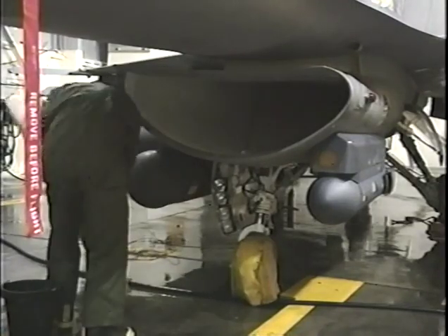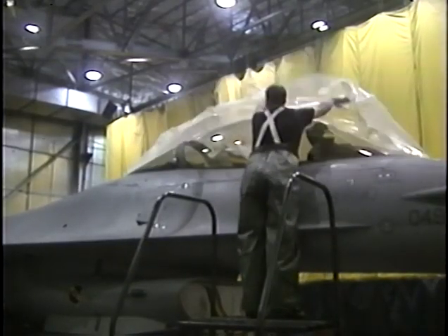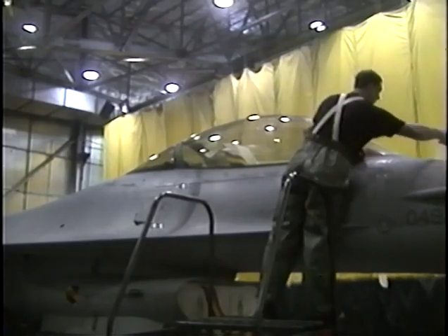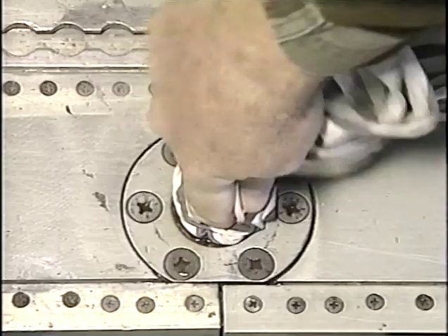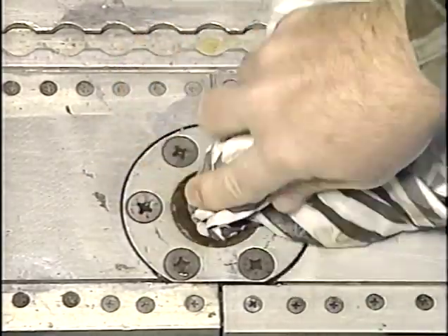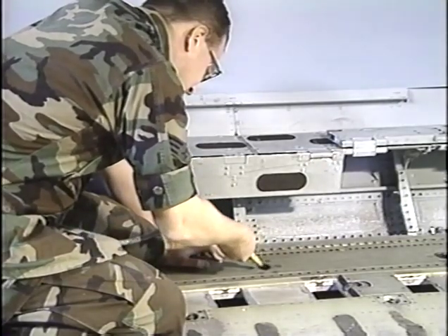When you have completed the wash and rinse process, remove all the protective devices placed on the aircraft and check areas vulnerable to water entrapment. At the same time, you should ensure all drain holes are free of obstructions. It's very important that you remove as much water as possible from water traps. It may be necessary to open or remove the panels or use forced air to dry these areas.